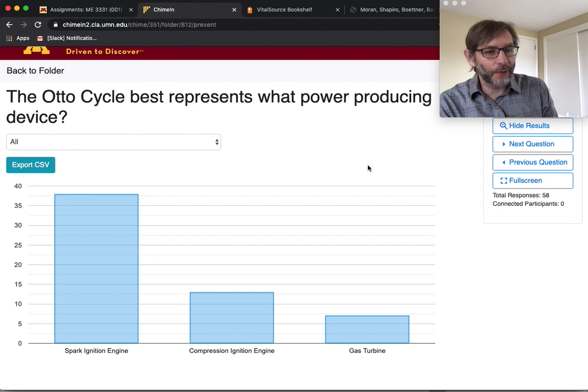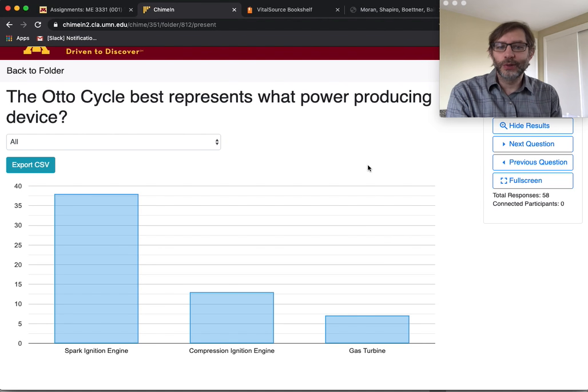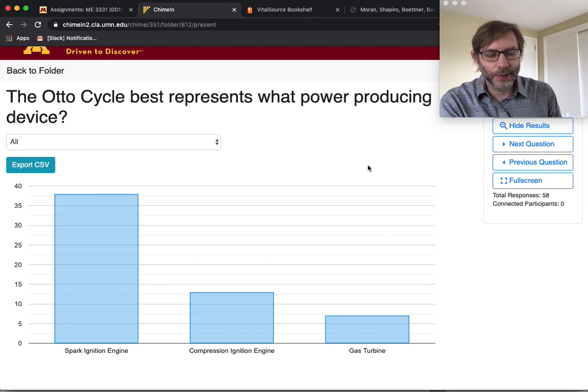Okay? But if you're in a two-phase system like water or ammonia or R22 or some kind of refrigerant, you have to use the tables. Do not give me the ideal gas law. You will not get credit for that because that is not the right assumption. Okay?